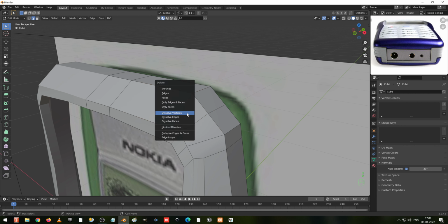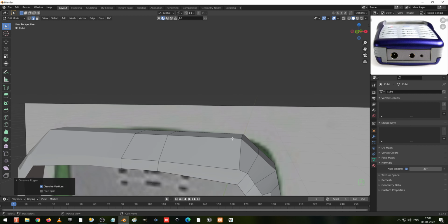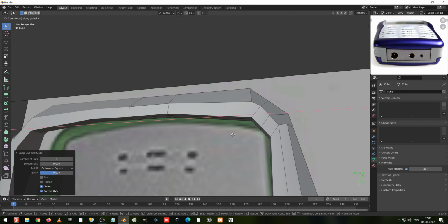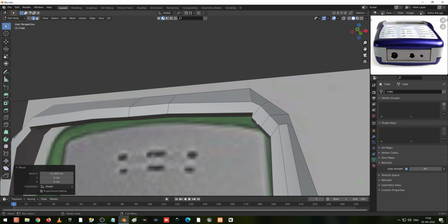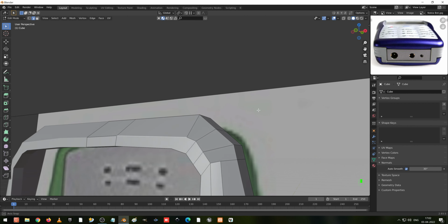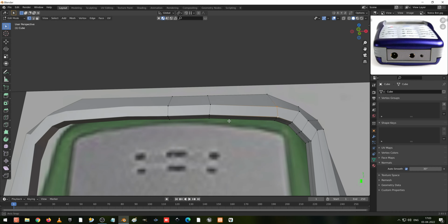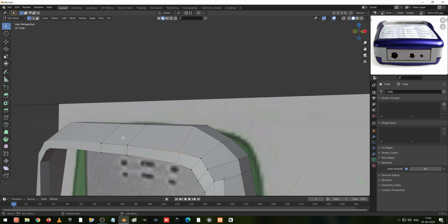This selection X, dissolve the edges, press Ctrl R. Here it's not creating, so what we have to do means Ctrl R, G in Y axis, sorry X axis, use this, and double G to move here, and this one, select this, double G to move here, press 1 on the keyboard and select this, press join. So now we have created one exact frame which is required for us.